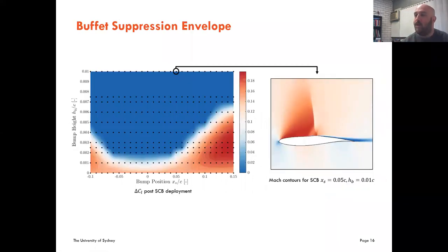Now, all this buffet does occur on your standard civilian aircraft, which is not the good news. And normally the flight computer just knows not to fly in that particular region. But is there a way of actually stopping buffet? If you look at the video on the left-hand side, once you restart, you will see in this region over here that we're slightly modifying the aerofoil.